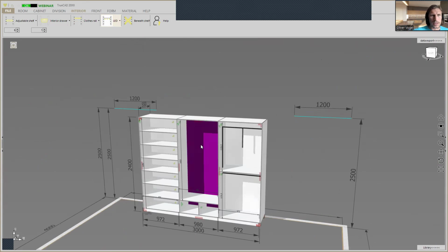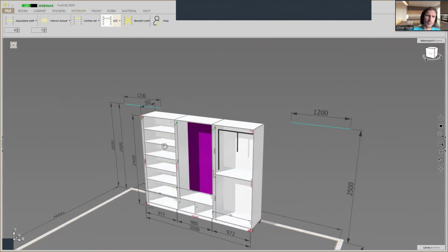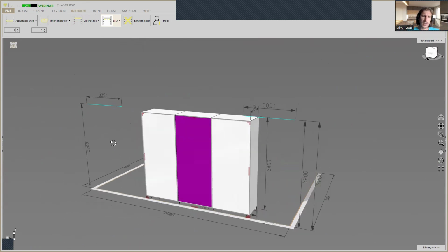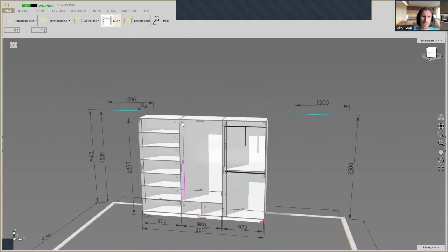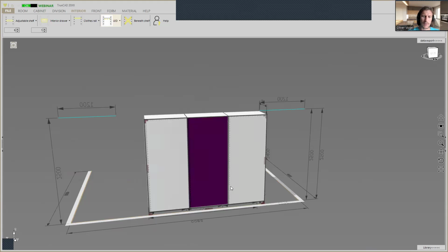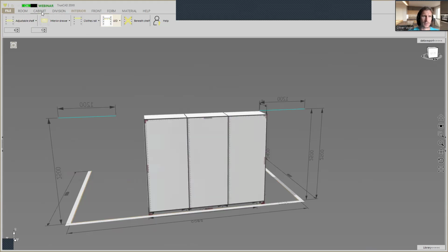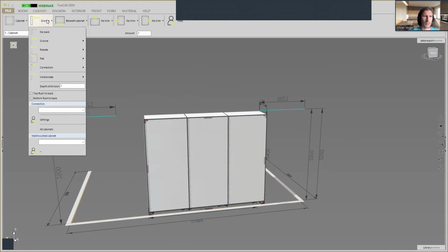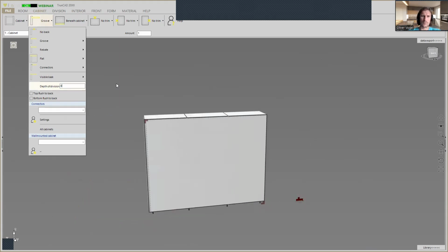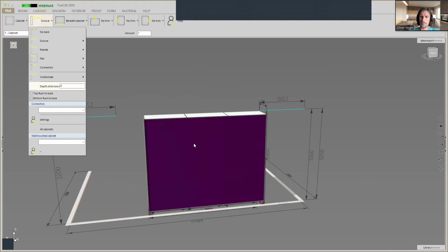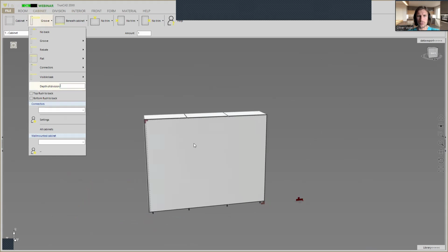Okay, here in the middle area, we want to take out the wall, but we just can take it out in the top area when the wall is divided. So that's why we go here to the cabinet tab, go here to the back wall, to the back panel. And here we need to change the depth of division from 1 to 0. Not from 1 to 0, then it's going through the whole area. We need to change from 1 to 2. Then it's getting divided here.